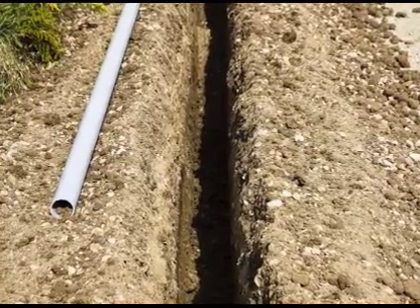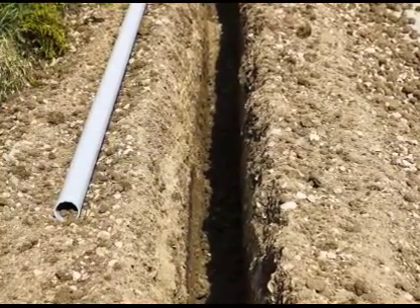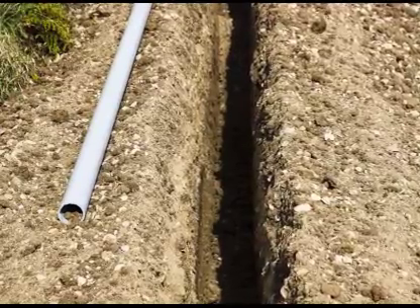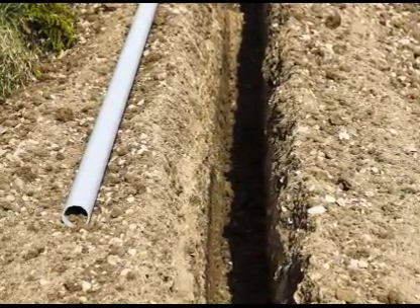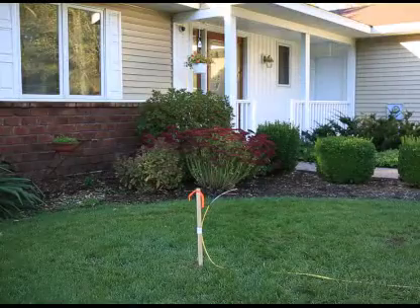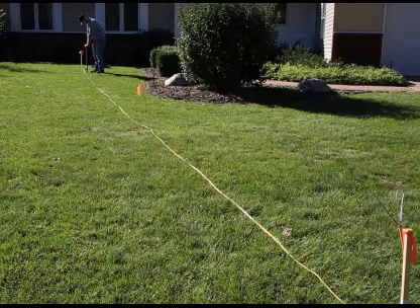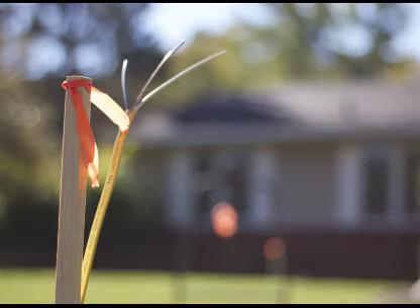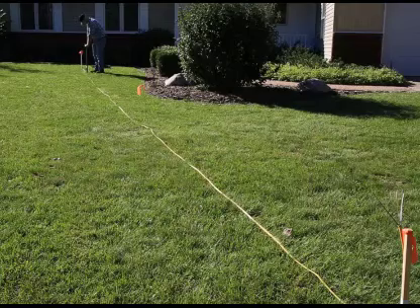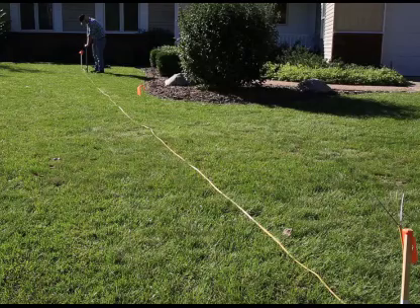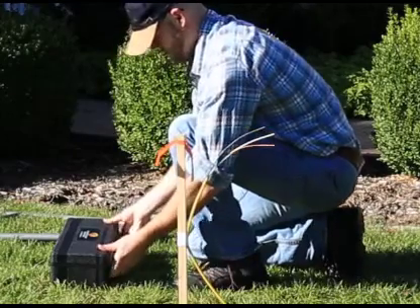In cases where the wire is contained in conduit, the conduit will interfere with the locator signal and not result in an accurate reading. Isolate the cable to be tested by disconnecting it at both ends. Make sure the cable is disconnected from power, components, or anything else that could transmit an electrical current. This forces the current generated by the transmitter to exit the cable at the fault.